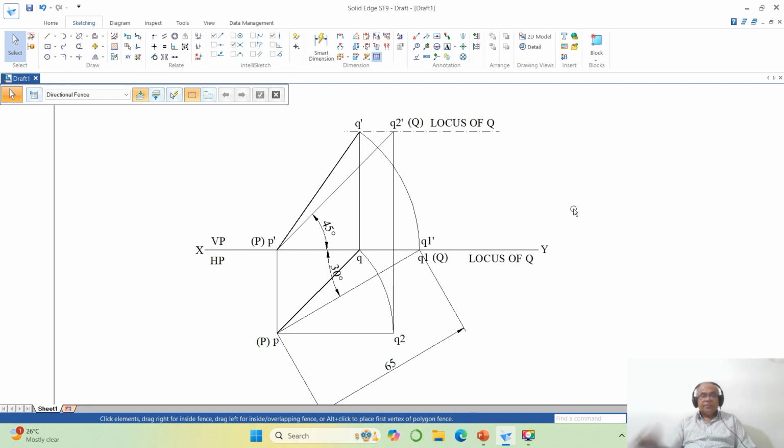Then I need to do the projectors, like the directions of projection. So click on point on element, remove endpoint and intersection. Go to leader. As we rotate this in this fashion, you will get this direction. Now here I take from Q2, I am drawing a vertical projector down, and from here I am rotating in the counterclockwise direction. Once you get this, I will project this till here, so that you get the exact dimensions. So how do I know that my problem is right?